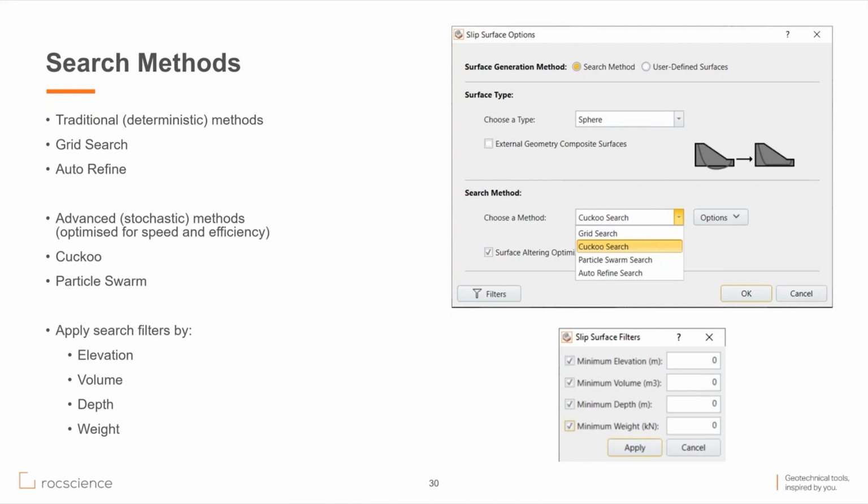Can we construct the groundwater surface model by time so we can see and understand the changing factor of safety of stability by time? You can, if you've got the groundwater surface and potentially different topo elevations. They would just be separate Slide3 files. Otherwise, you could certainly model that in stages in RS3.